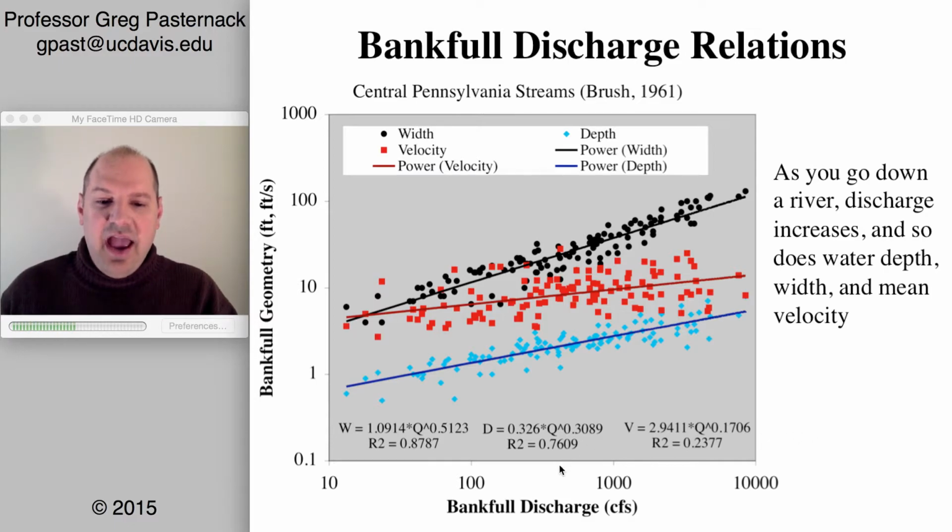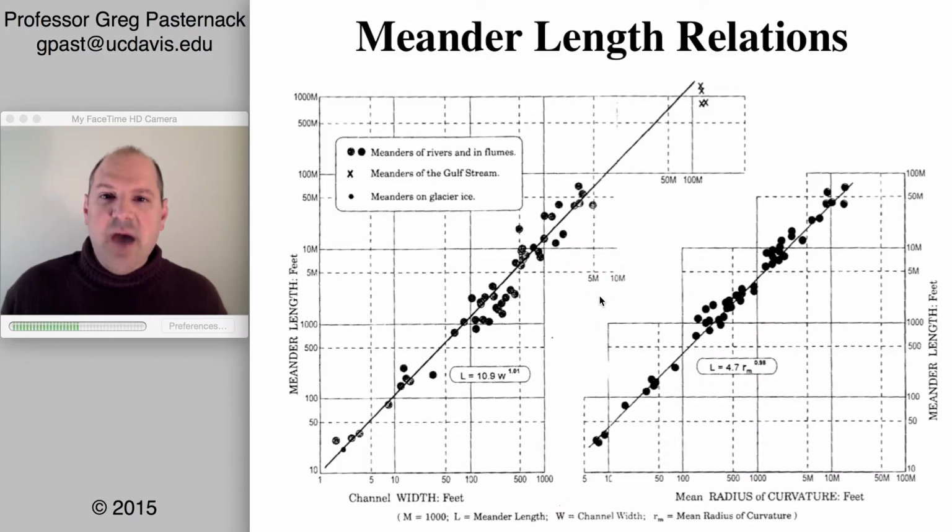So if you could say, okay, I want to design a river to have, say, 1,000 CFS, then I could size it with these depths and widths to get that. To get the velocity, of course, you can adjust slope or you can adjust bed roughness. There are some other basic empirical functions that exist that can be used in river restoration as well.